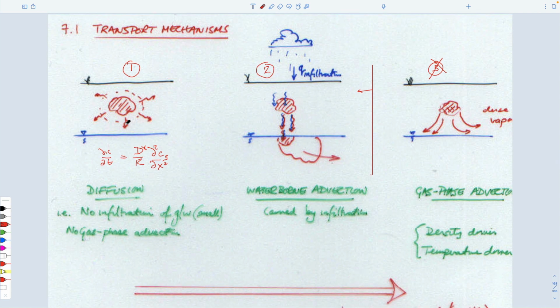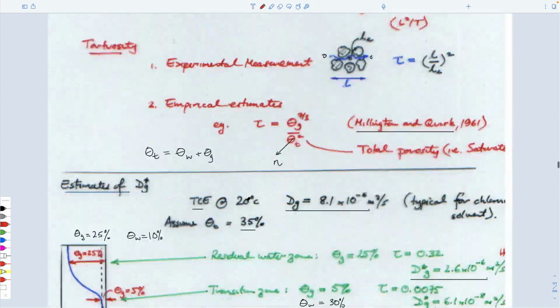It turns out that this kind of motion is the least effective and least rapid way of traveling. Of course, it might off-gas to the surface and volatilize off and be present in air monitoring. But the rate at which it can move is probably much faster, and with much higher mass loadings, if you look at it being transported in aqueous form. So this is the other method that we look at. And of course, you can imagine that if it's being transported by water, a portion of this transport will be retarded according to the aqueous retardation coefficient. So let's see how we would solve that particular problem.